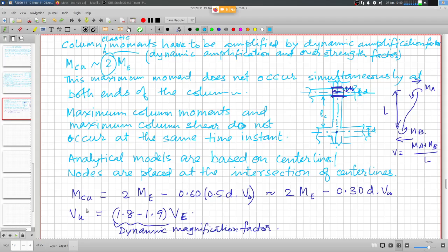And if that axial load is very small, then it is possible to allow for some inelastic deformation in that column, but total moment capacity reduction in a column at any level should not lead to anything less than a 10% reduction in total moment capacity as predicted from an elastic analysis, right?